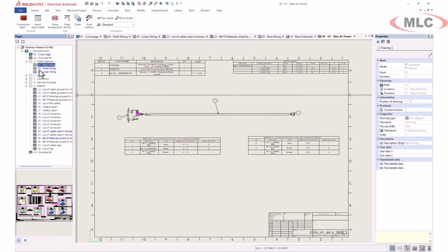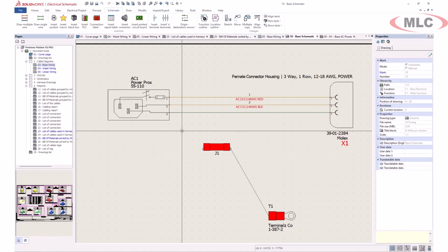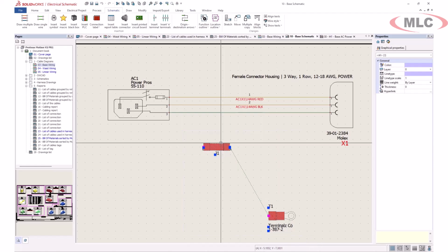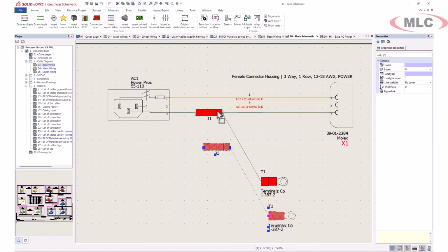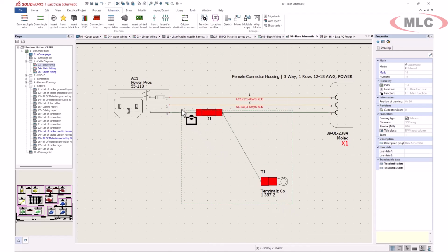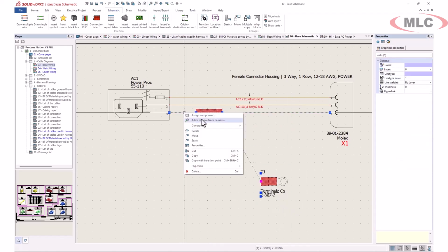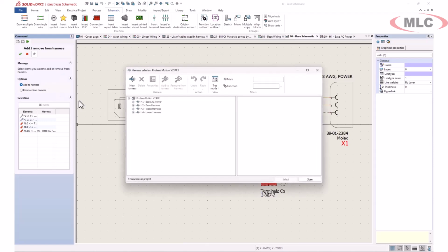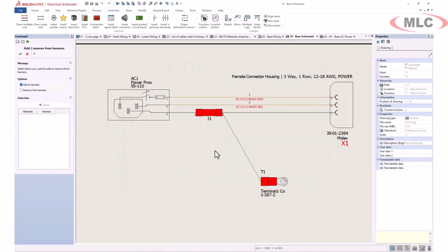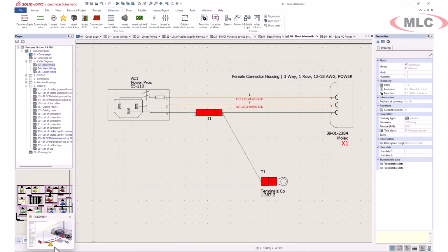All right, the project drawing looks all nice and pretty, but how about we do some design? One task today is to add a splice to extend my ground loop directly to the chassis. This means I will have to update the 2D design, the 3D route, and the flattened harness drawing. Let's start by finishing the schematic representation, extending the ground circuit to the chassis via a ring terminal.